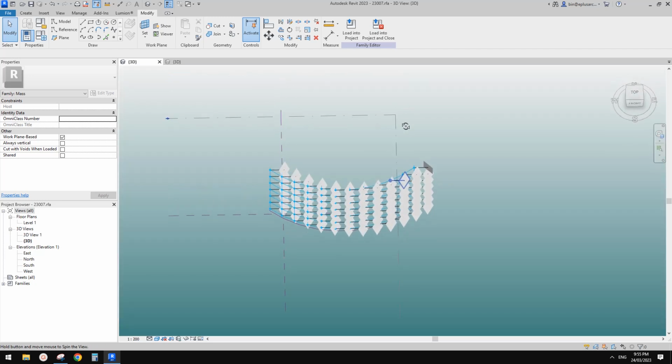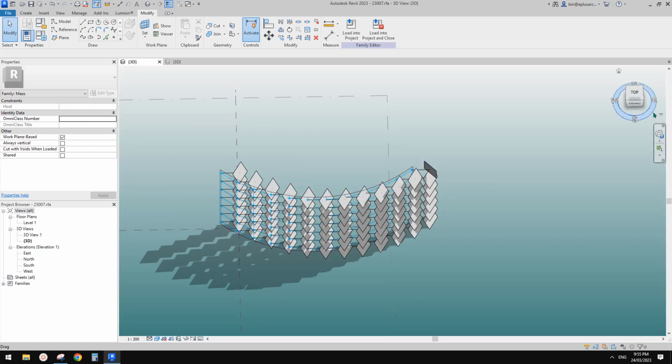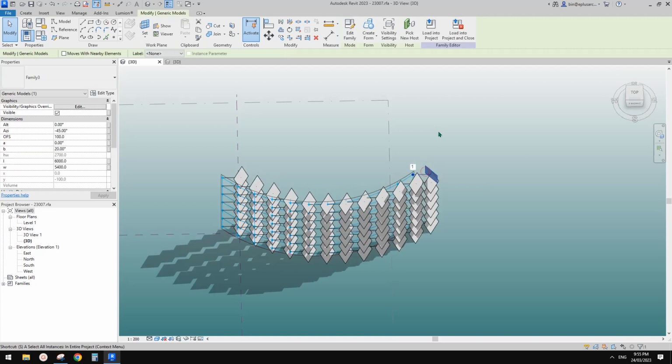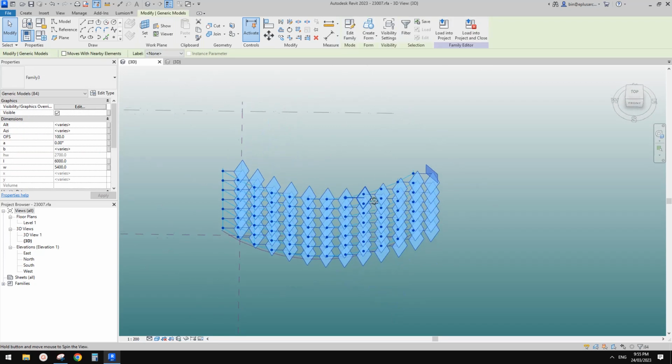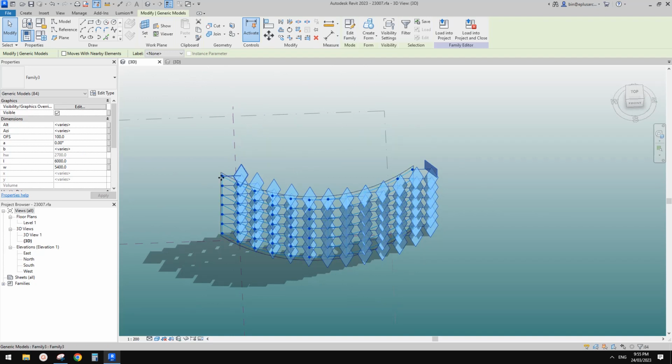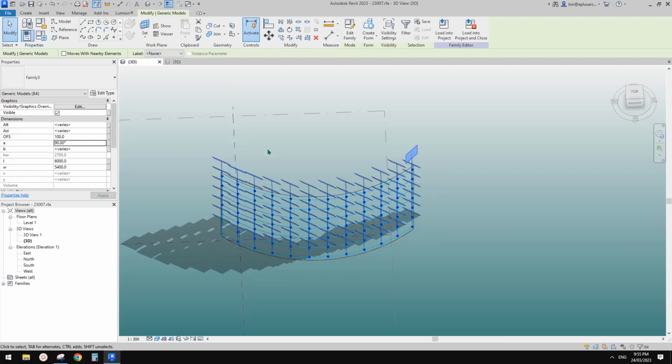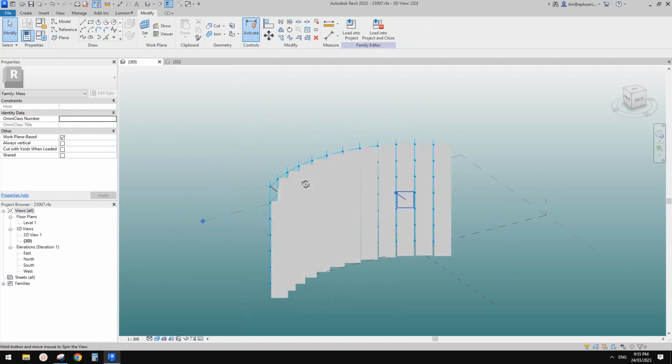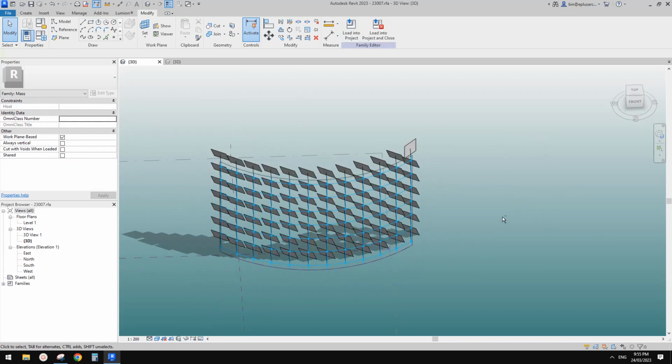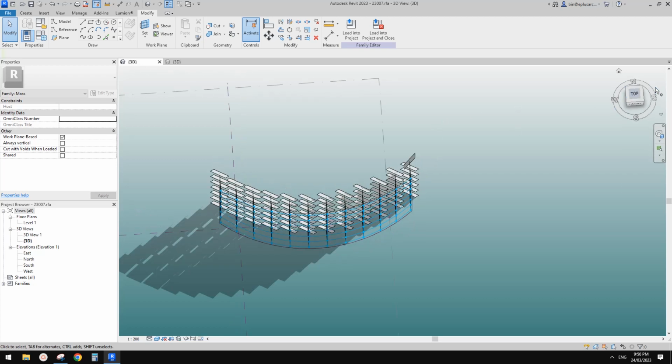Oh, hang on. Those families are still facing east. Okay, that's fine. I'll select all, because previously when we did this family, we added a rotation parameter to control the direction. So it should be A. If I type in 90 degrees, yeah. So now all these panels are facing north.